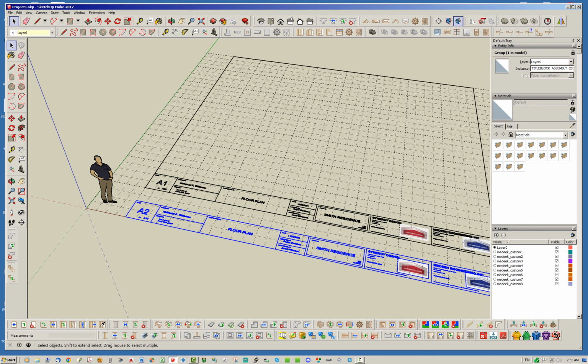And just like any other assemblies that I create with my plugins, you can basically lock these so you can't modify them again. And the way to do that, of course, is just change this entity instance name. Notice it has a keyword title block_assembly and then a bunch of random timestamp associated with it. You can replace that timestamp with something.